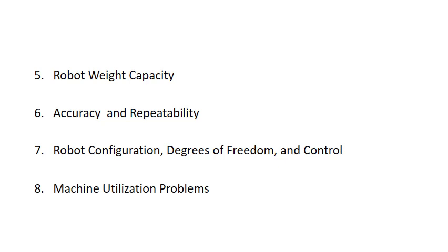In cases where a long machine cycle is involved, the robot is idle a high proportion of the time. To increase the utilization of the robot, consideration should be given to the possibility for the robot to serve more than a single machine.